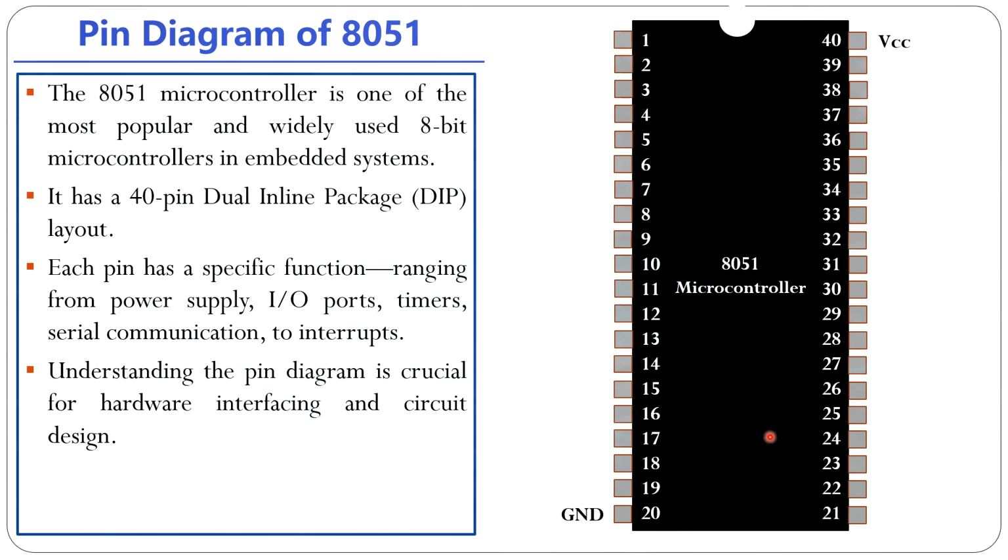First of all, we can see here the pin number 20 connected with the ground. Pin number 9 is connected with the reset pin. Pin number 9 is called the reset pin. Next thing, we are using here pin number 19 and pin number 18. We can say pins 18 and 19 are connected with the crystal oscillator. You can see here this is just a symbol for a crystal oscillator, XTAL1, XTAL2, and this crystal oscillator is connected with ceramic capacitors. So we will see this in the interfacing.